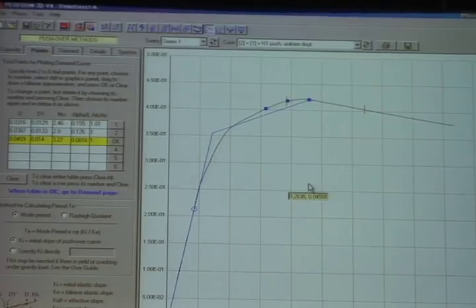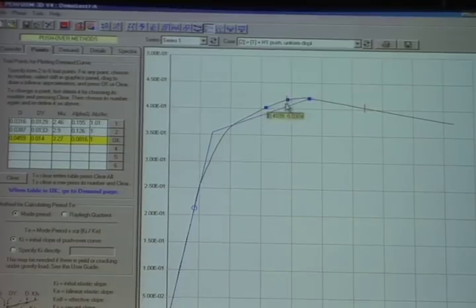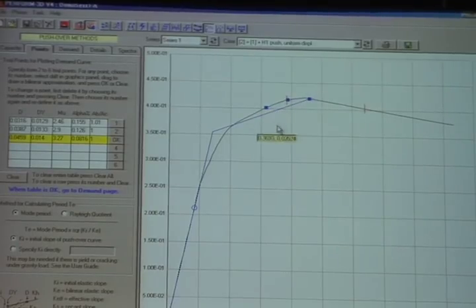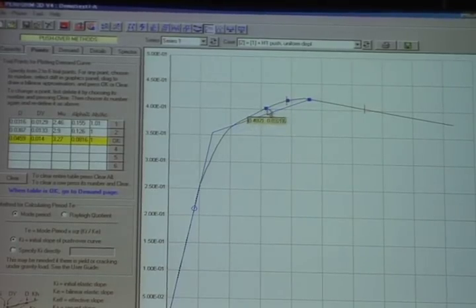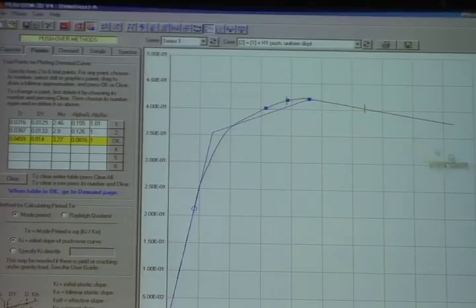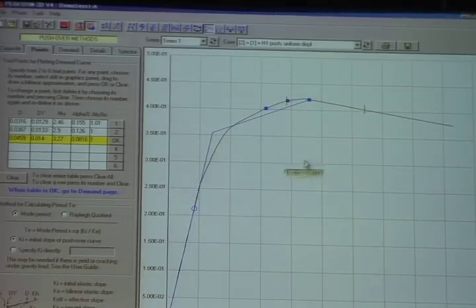And what I've done is generate here 3 trial points. And I'm going to find out that this is along the capacity curve, which is the pushover curve. I'm also going to plot a demand curve. And let me do that next.